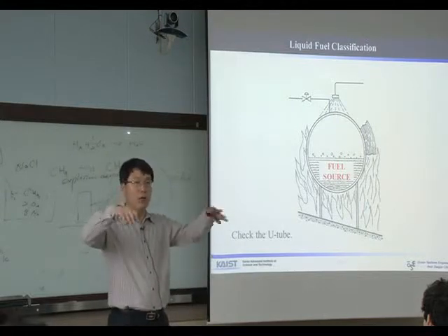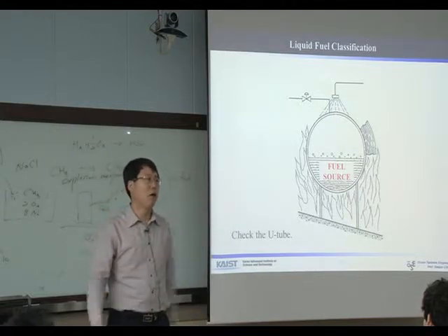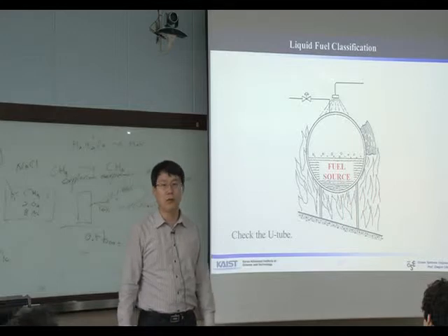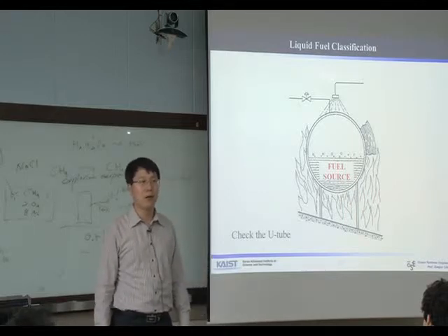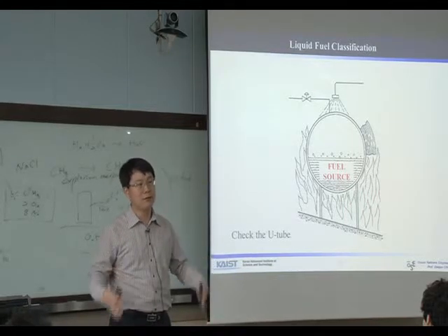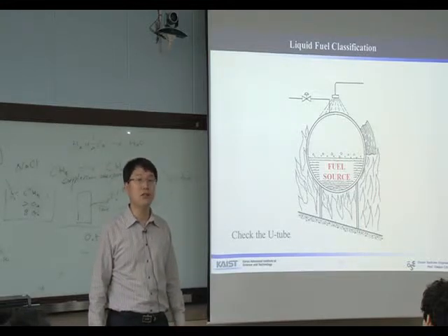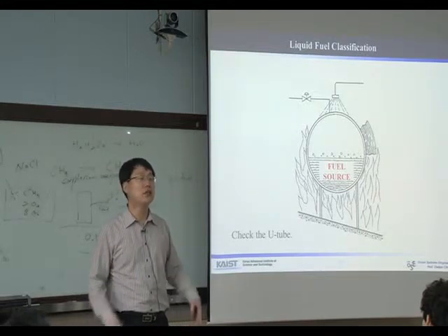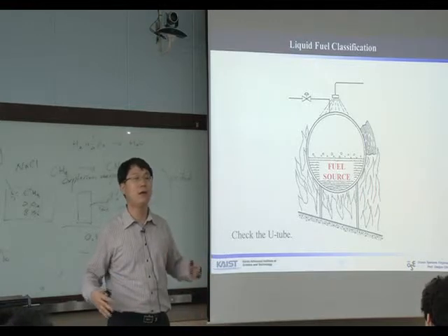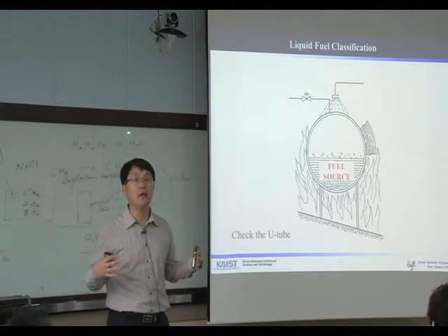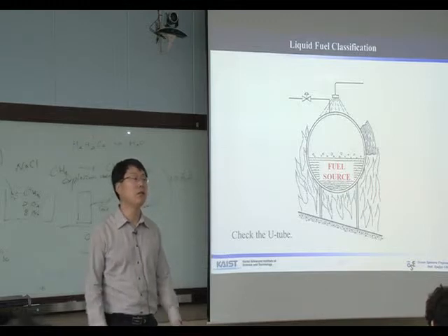So even though we pour some water through the deluge system, the effectiveness of the deluge system is not that substantial. So it just delays the explosion, it cannot prevent the explosion.